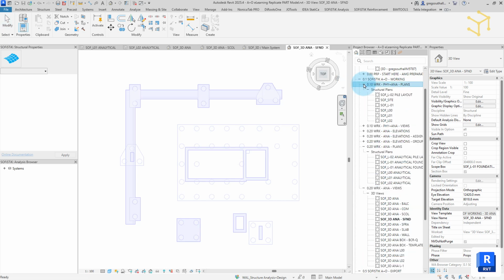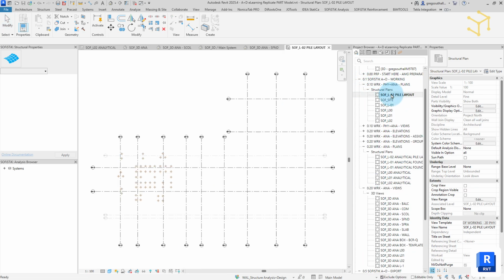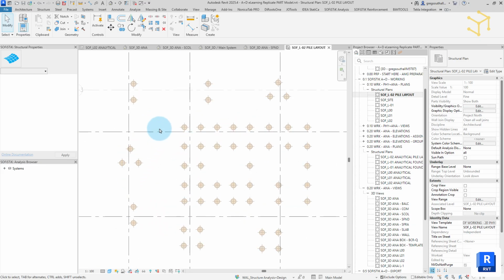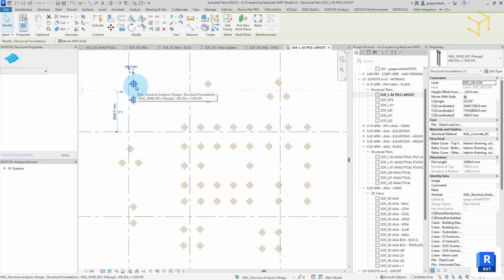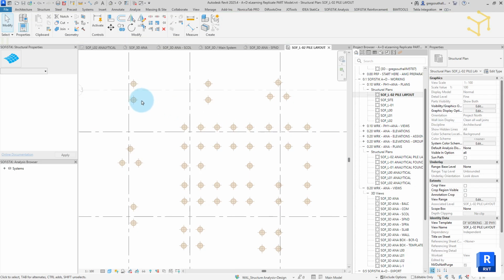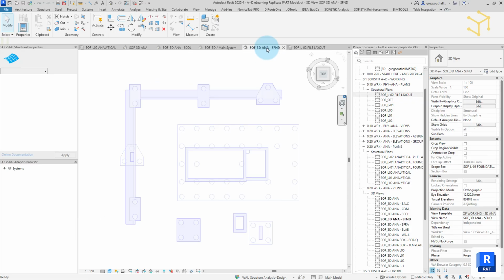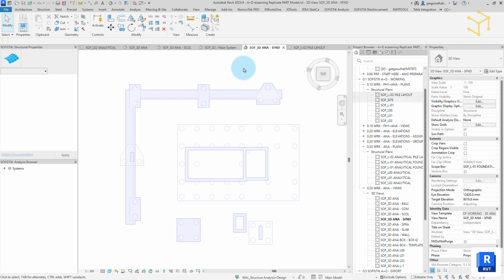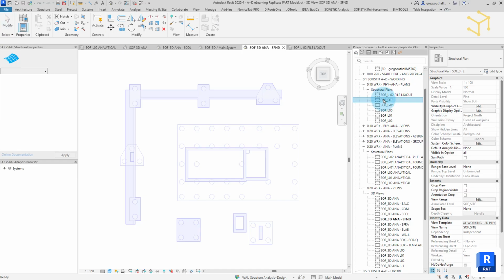As we copied the physical model, we can also inspect using the physical and analytical views in our working directory. Here we observe the piles, again inspect their properties including the pile number assignment by mark. We'll later automatically assign the pile reference to our analytical supports in readiness for calculation of forces to the piles, followed by the generation of an analytical pile schedule in Module 6, which includes updating the forces parameter values to the piles. You will observe in Module 6 just how quickly and easy the update operation is to provide pile forces data output in this BIM workflow.